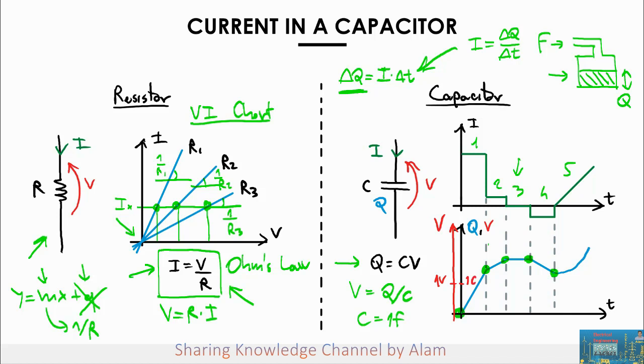Well, then in that case, the waveform of the voltage will be exactly the same as the one of the charge in this graph. So it will follow exactly the same behavior. Naturally, the voltage is represented relative to a different vertical axis, but I tricked the numbers so that they will perfectly overlap. But anyway, the main concept here is that once you have the shape for the waveform of the charge, the behavior of the charge over time, the behavior of the voltage will be exactly the same. So where the charge is increasing linearly, the voltage will also increase linearly, and vice versa.